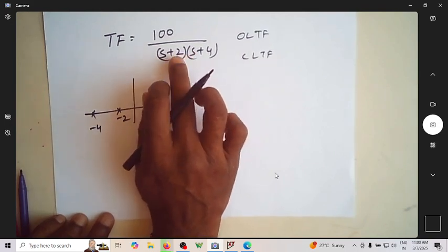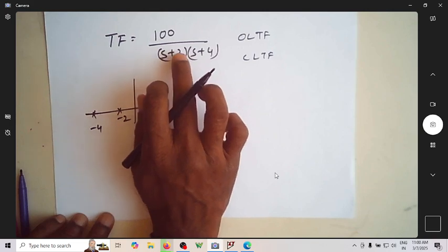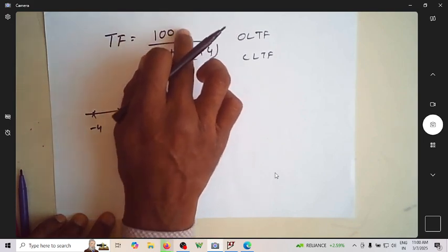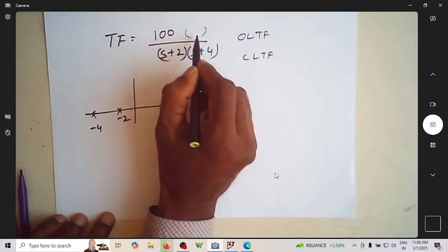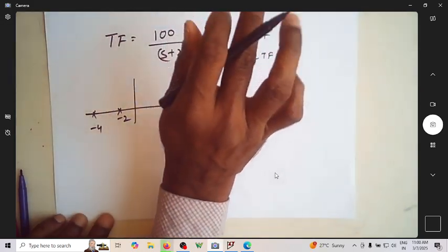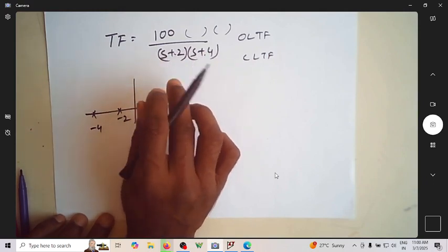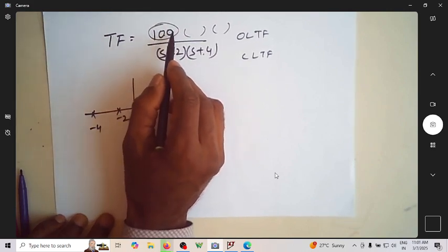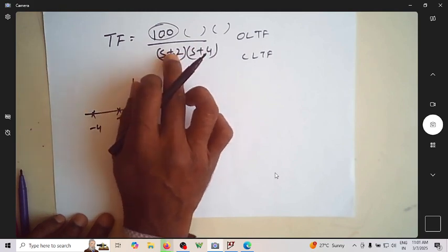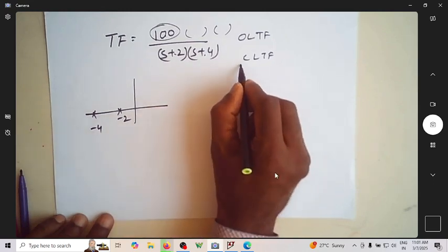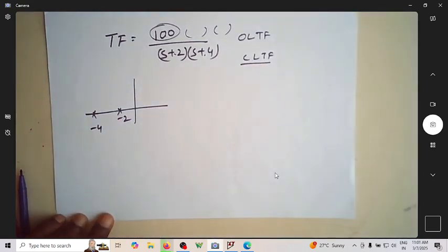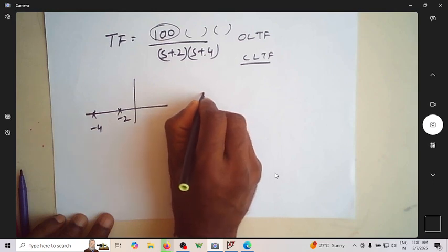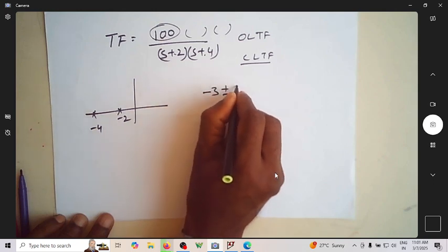Where do these poles go? They have to go to infinity, because they don't have their pair at a finite point. You can see that there are no finite zeros. Where are the zeros now? Zeros are at infinity. When zeros are at infinity, as the value of this 100 is there, 10,000, whatever comes, you can just give me the closed loop pole position. And it is interesting to see the pole position will have a real value -3 plus or minus jx.